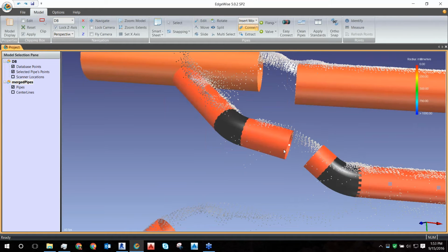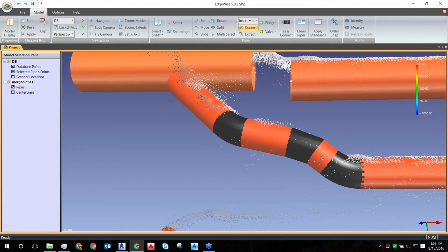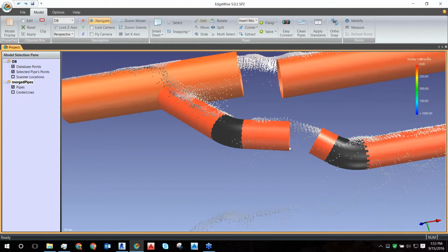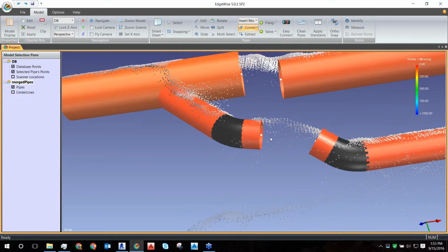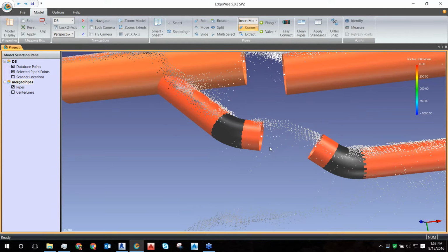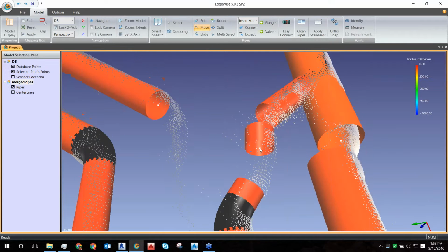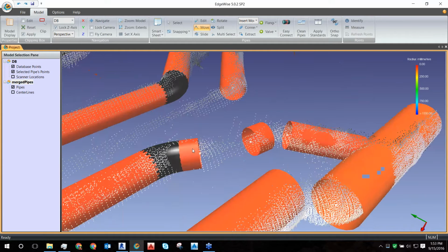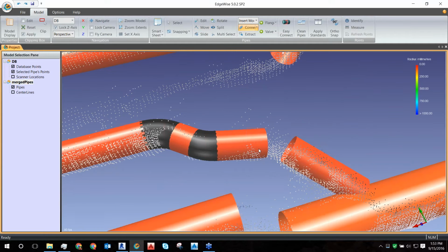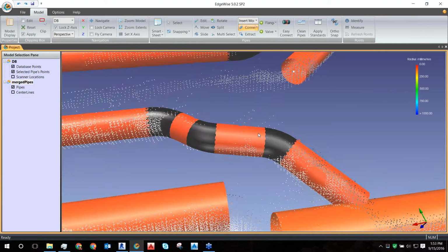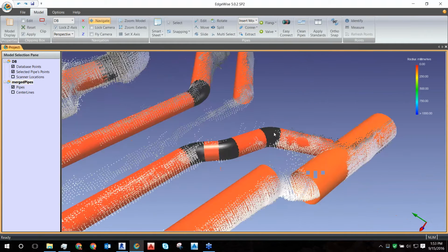I would make that the upper limit of what you could expect to do in a single scan, and typically, you would want to capture spaces that are much smaller than that in more detail. So this handheld scanner does not replace a terrestrial laser scanner, particularly for large spaces. Well, I wouldn't recommend it if you need to get it all in one go. We can, of course, stitch together multiple data sets. Okay.